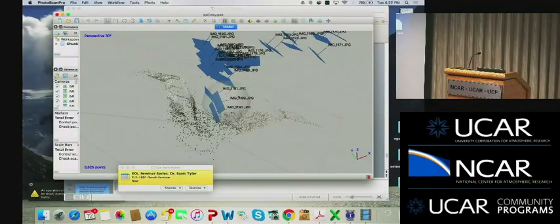And what you see here is each one of these little blue frames is the estimated position of where my camera was. Now, I was inside, so I didn't have any GPS on the phone. It wasn't working. But the camera positions have been calculated by common points where two or more of the photos saw the same place on the ground, some piece of the floor or my foot or something that was recognizable. Okay? From that, gets the camera positions. Okay? From that, then, we can fill in the rest of the points.